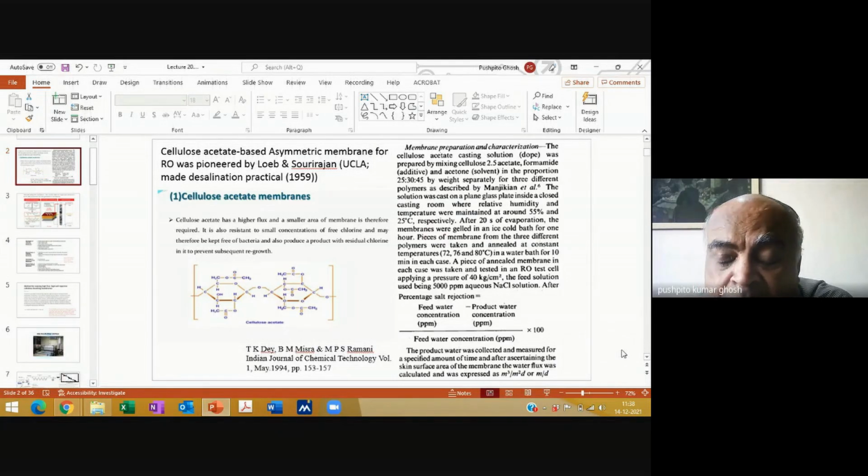It's a good question. You can ask yourself, what is really forming pores? Why is it that pores are formed? After my acetone has evaporated, I'm still left with the formamide because its boiling point is higher. But subsequently, when I put it into water and I'm gelling it, what then happens is that finally the formamide is getting dissolved and leaving the system, and wherever I had formamide, I actually end up getting a pore. Is it clear? Yes, sir.